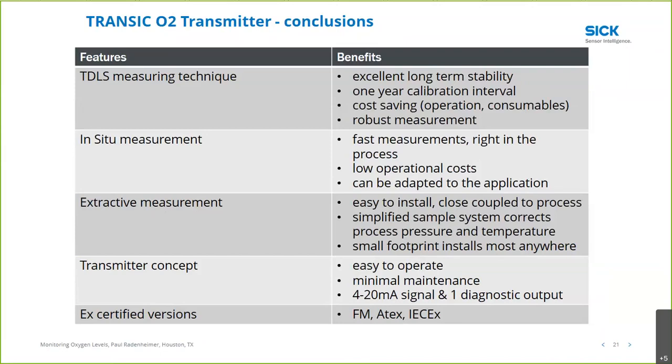It's not uncommon for people to take the most convenient place for installation, and on one particular tank, we saw an upright 6-inch process pipe that made a 90 degrees turn after about 4 feet, and after another 4 feet ended in a process flange. So we basically had about 8 feet of dead leg. The transmitter was installed at the end of that 8 feet of dead leg.